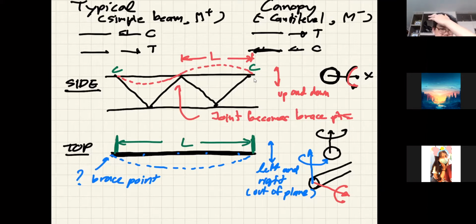And for this, the first case, when you look at the side view, you may say, in this case, K is equal to 1, because it still resembles a simple beam somewhat. But for the second case here, because the member is solid entirely, and we are talking about the entire member coming out, even though the unbraced length may be longer, you may take K as 0.65.